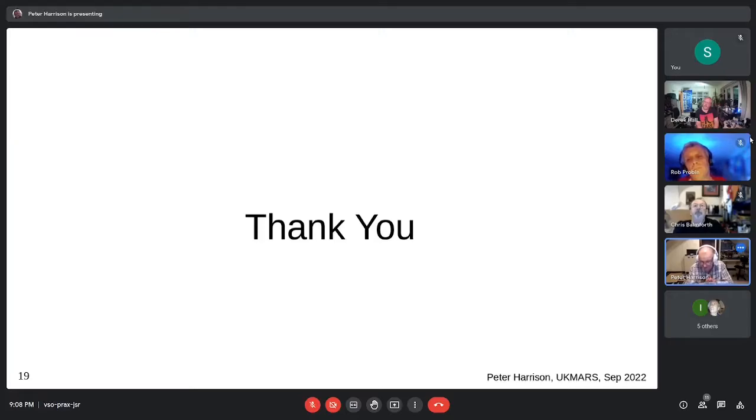And the other is, I made a lot of noise earlier about how hard PID controllers and PD controllers are to tune. And the great benefit of having feed forward control in as well is it doesn't matter so much. If you get your PD controller wrong, it's not as important because everything will kind of sort itself out. So it's easy to do, and it provides you with a way of getting good performance with relatively poor configuration.